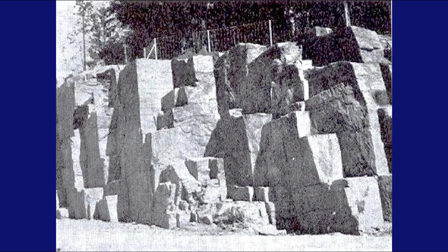This shows an outcrop of rock, and I often use it as an example because it is a very clear-cut case. In that slide, you can see that the rock mass consists of cubical blocks of rock, and it's clear that there are 3 joint sets. 2 of these are sub-vertical, and 1 is sub-horizontal. One can get an idea of scale from the fence posts at the top of the slope there, the top of the cutting, and in this lecture we're going to assume that those fence posts are 2 meters high. Obviously you need to take into account the scale of the photograph as well.